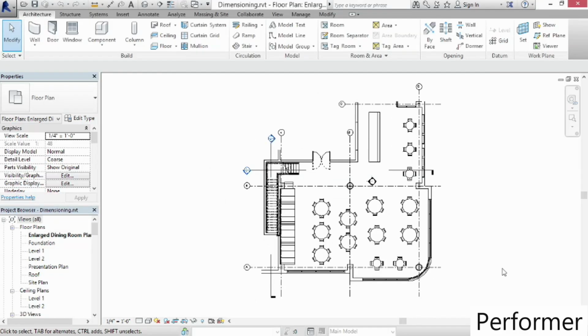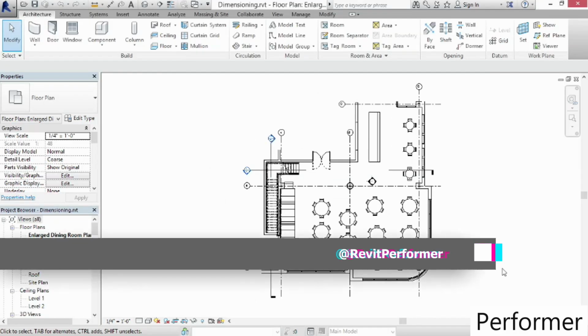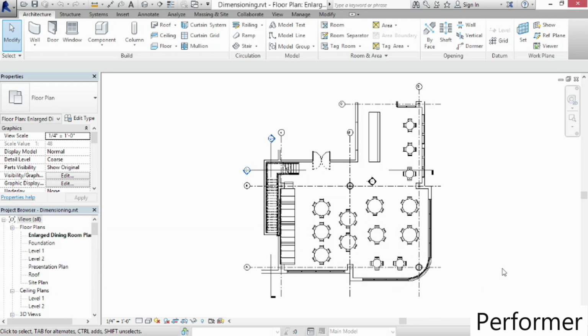In this movie, I'd like to take another look at dimensioning. In a previous movie, we looked at dimensioning, but there we used the dimension tool as a modification tool to help us move our geometry around to get our walls placed precisely or our doors and windows. And that's a perfectly valid use for the dimension tool. Another valid use and a very critical use of the dimension tool is to actually create dimensions on your drawings for the purposes of printing out those documents and reporting what those values are to the recipient.